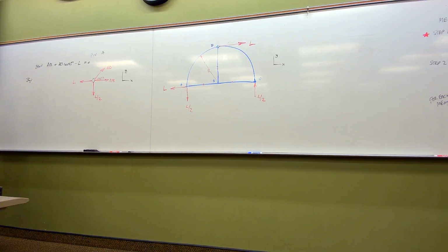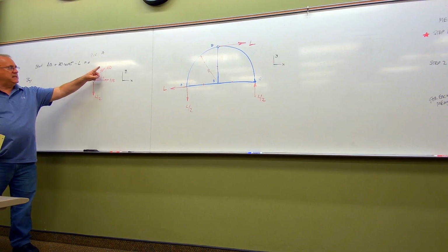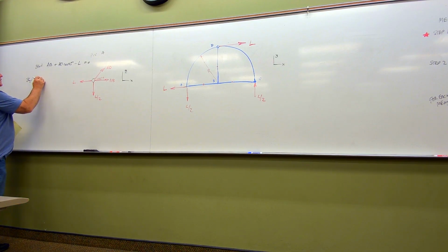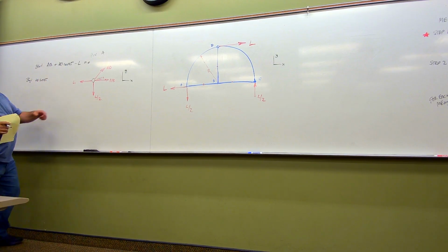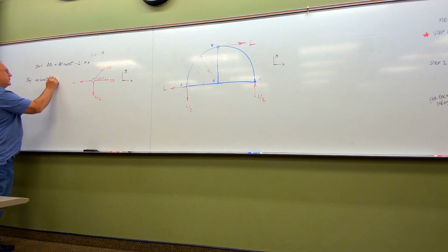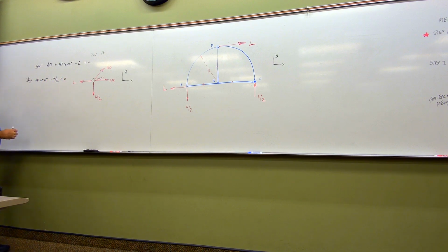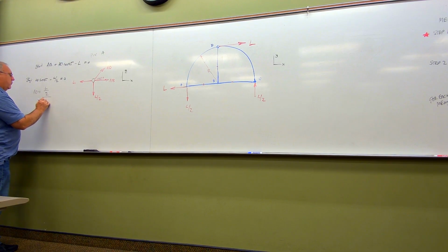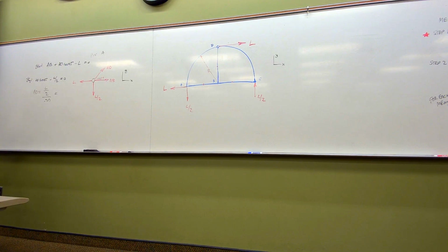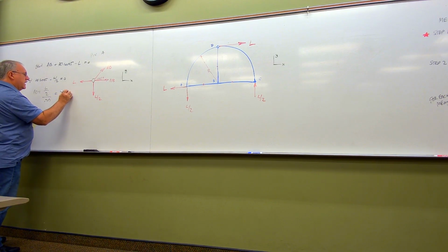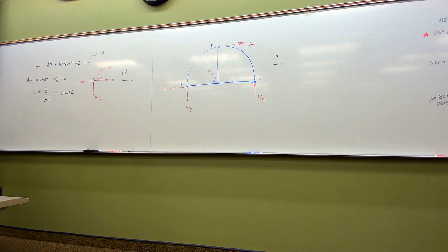And in this case, I'm going to have AD here tending towards positive y, but it's going to be AD times the sine of 45. Minus L over 2. And that's equal to 0. So that means that if I solve for AD, AD is going to be equal to L over 2 divided by the sine of 45. So this whole thing divided by 0.707. And folks, when you plug that in and crank that out, we're going to end up with AD being equal to 0.707 times L for AD.